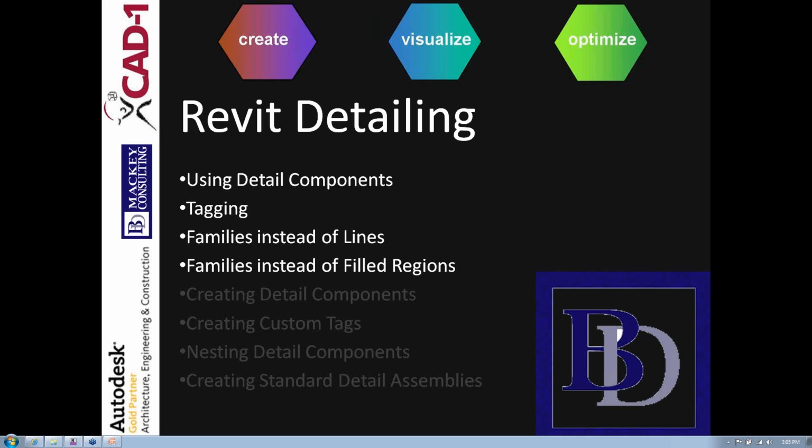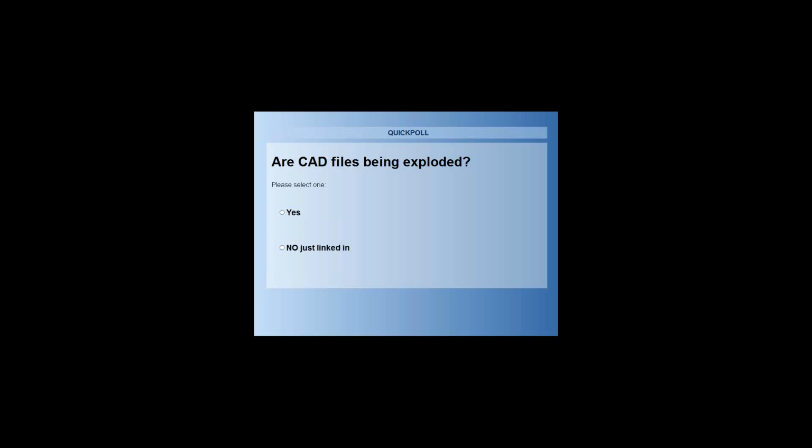So this one, I hate to do this, but I've got to see how many of you are going to make me cringe on this one. Of those imported AutoCAD files and not linked CAD, are you exploding them? Ooh. Autodesk actually came out a couple years ago, and I think they retracted the statement or hid the white paper. Yeah, it's buried now. But are you exploding those?